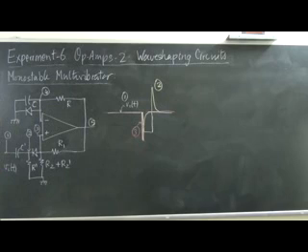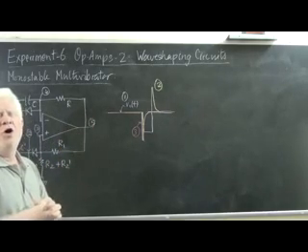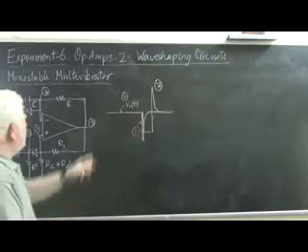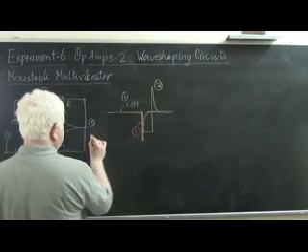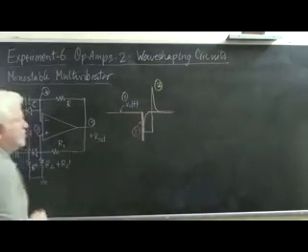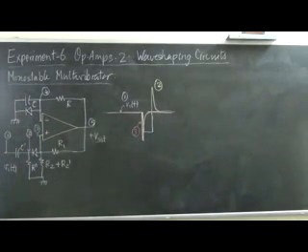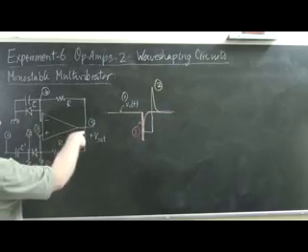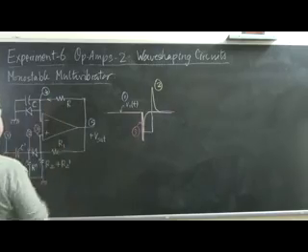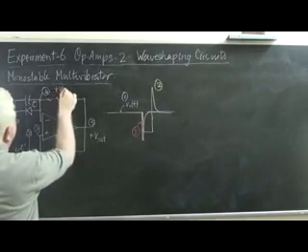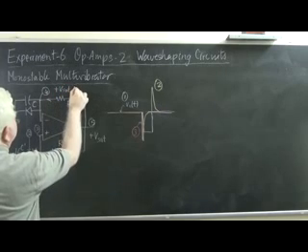But let's go back in time a little and see what was the state of affairs before this input pulse was applied. All was peaceful. The output was at plus Vsat. And on the inverting side of this op-amp circuit, the following things were happening. We have plus Vsat over here. We have this at ground voltage. And so a current flowed through this part equal to plus Vsat by R.